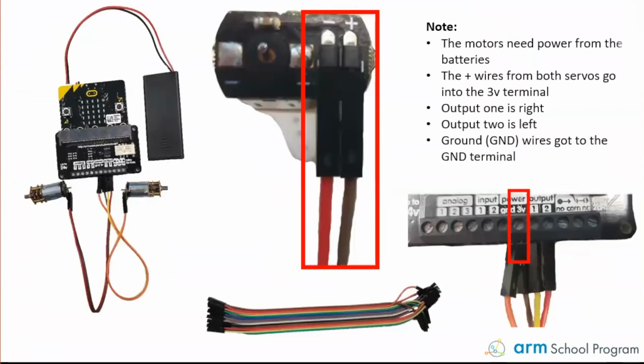So this is a picture of the sort of finished product, and you can see there, look, you've got your motors and the board all plugged together. And students, if they've not played around with electronics before, it's worth pointing out some of these things. Like if you're using this specific automation bit board, they need to put the power 2 pins in the same hole, which seems kind of counterproductive, but that's how that particular board works. If you're using a different control board, there are several motor control boards available. Some of them have additional 3-volt outs, others don't. So depending on what board you're using, if you're using this one, then this solution works fairly well.